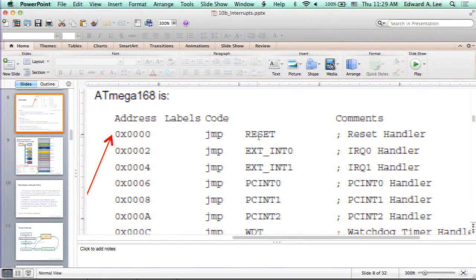Okay? So that would typically be a bootloader. So the bootloader will be a chunk of code that you've put in your flash memory or in some form of read-only memory that will look for a program to execute at some location, load it into memory, and then jump to that. Okay, that's what a bootloader does.